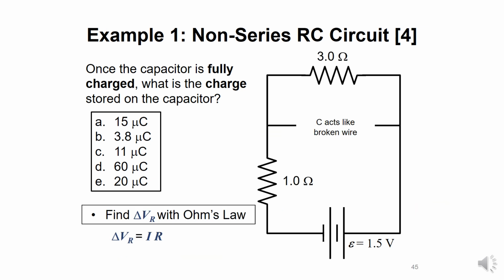Now back to our previous picture. We have the current. We are trying to find V3 up here. We'll just use Ohm's law. We can use Ohm's law for a single resistor or for multiple resistors or for the whole circuit. In the previous slide, we used Ohm's law for the entire circuit. Now we're going to use Ohm's law just for R3. That will give us V3.